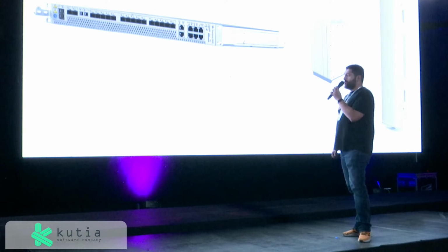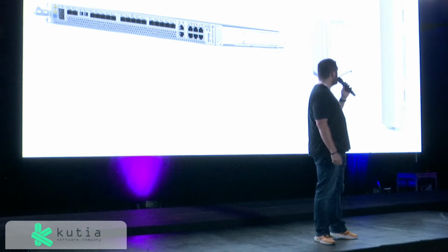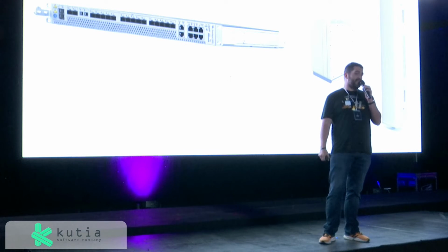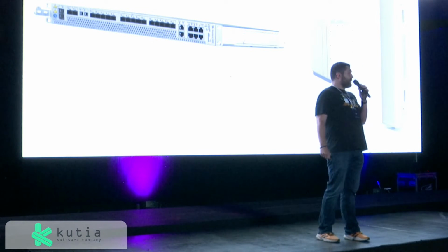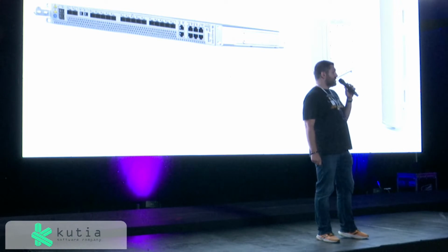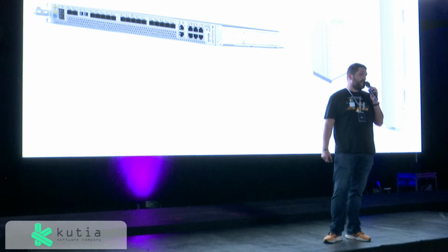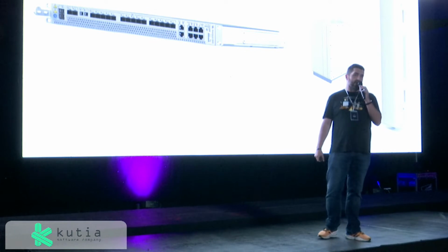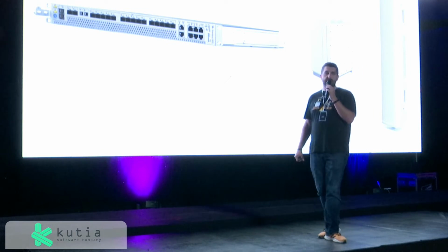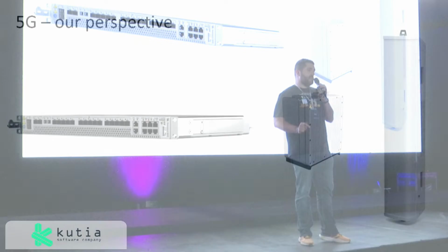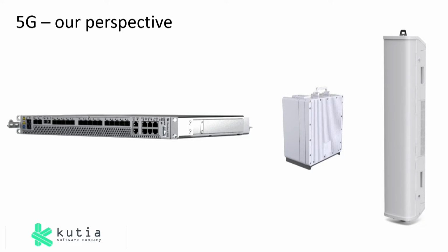And finally, the part you actually see around town is the antenna. This is usually the part of the base station you see deployed, because it actually needs to have some sort of visibility for you to be able to connect to it. Antennas have come a long way from the, I don't know, pieces of metal we are using perhaps still for our TVs. They are now much more fancy. They're a combination of many, many antennas which actually pinpoint the signal from the base station to you. This is something called beamforming, and it's also all the rage in 5G, because this actually lets us give you, as the end user, better connection while using less power on the RBS side, on the base station side.